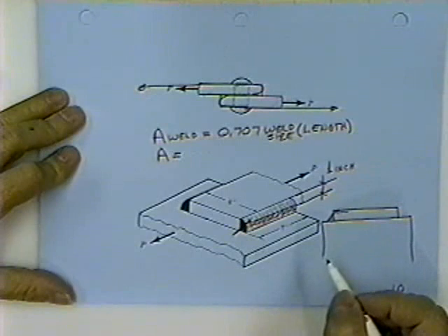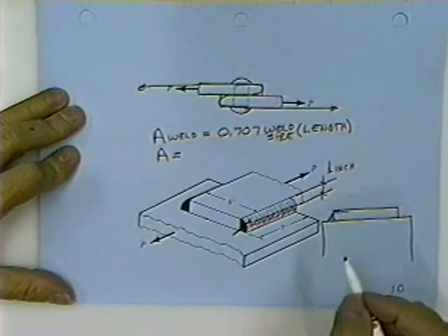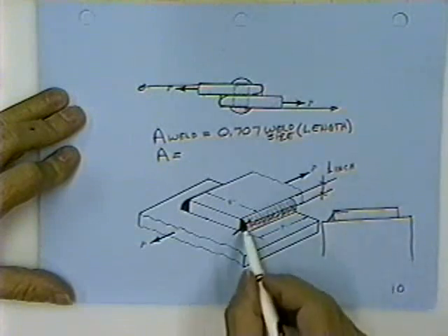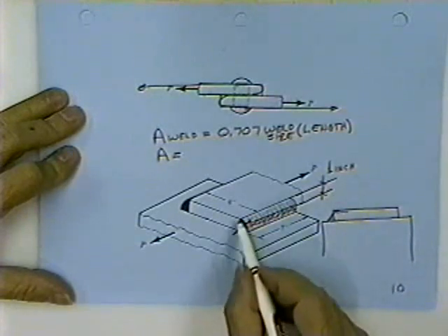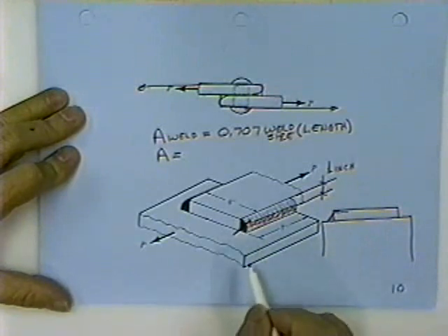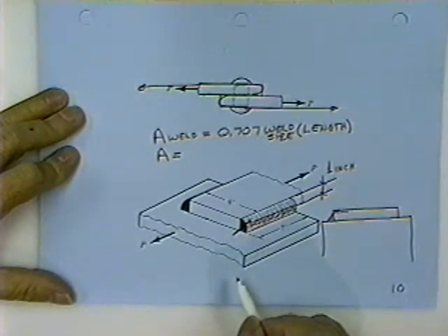So if you make him stay away from that corner and don't burn it off, then the inspector can come by and see there should be about a 1/16 of an inch gap between the weld and the corner of the plate all the way around. It's real easy to inspect. So the weld that they have shown in this figure shouldn't really go all the way to the top. We'll assume it does, but it really should stand down from the plate about 1/16 of an inch.